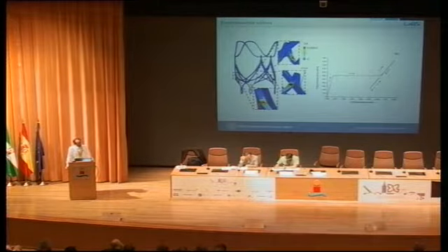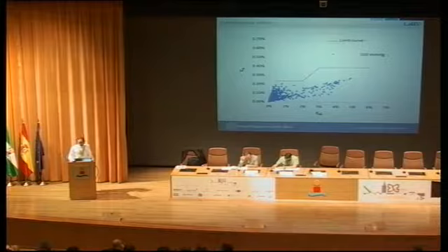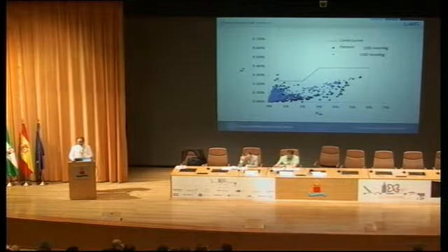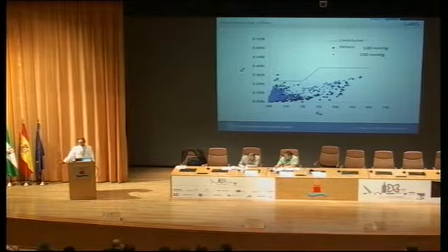And again, it's possible to have a description of the solicitation of the strain on the stent frame. The gradient that we apply in the in silico simulation is 100 millimeters of mercury, and we can observe that using patient-specific data, the stress changes. So it's important to know that if we do an experiment in ideal condition for certification purposes, not necessarily what we can expect when we apply the device in vivo is the same result.